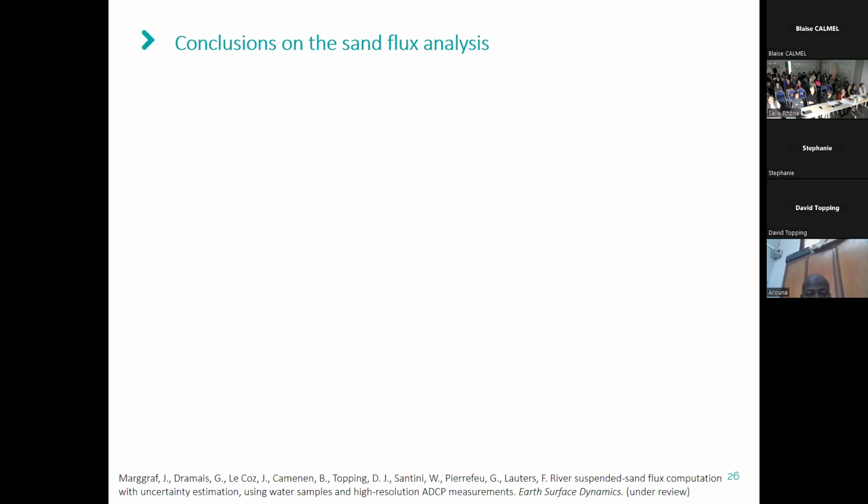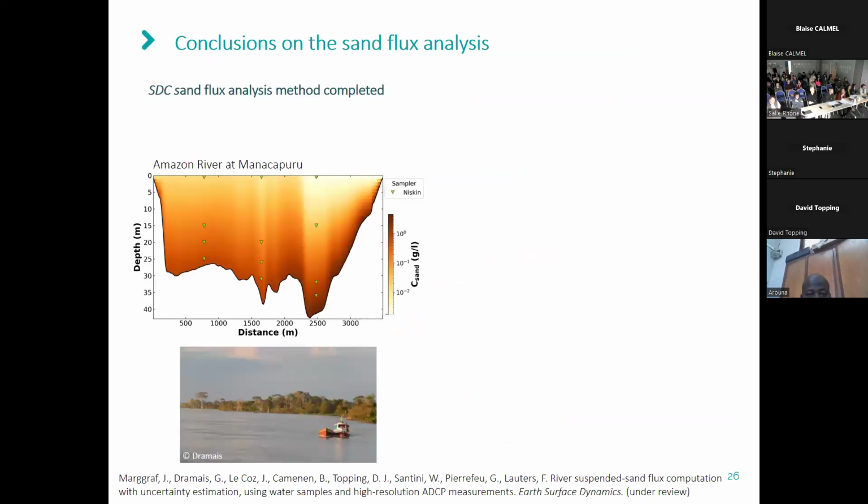To now conclude on this sand flux analysis, I completed this SDC sand flux analysis by also using a vertical integration with Bayesian modeling, which I first only used for the vertical uncertainty, but then also complemented the methodology itself. And when comparing this SDC method with the ISO standard results, we may observe relatively large differences. However, we have to take into account that no reference exists, so we cannot really evaluate which is the true and valuable method. And we can also see that there is no obvious bias.